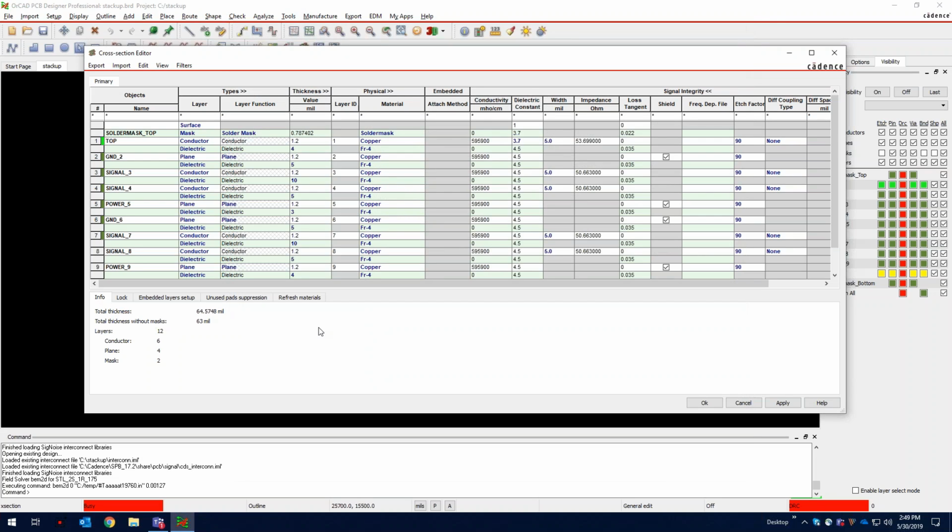So this 10-layer stackup is good because of the tight coupling of the signal and the return planes, the shielding of the high-speed signals, the existence of multiple ground planes, as well as a tightly coupled power and ground plane pair at the center of the board. And just by default, a 10-layer board is going to have tighter coupling just because there's 2 extra layers in there.